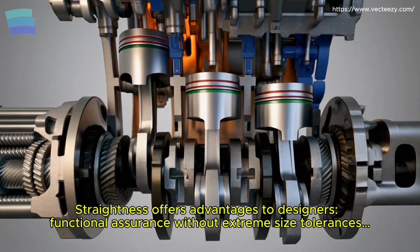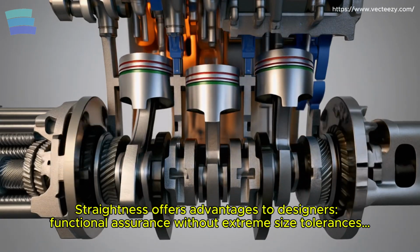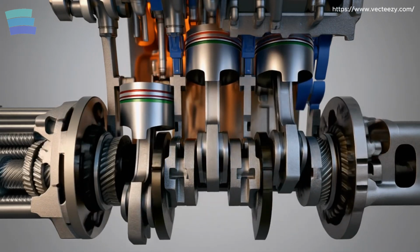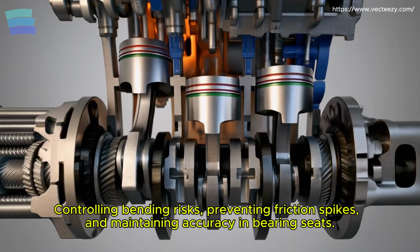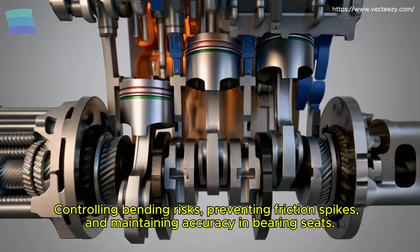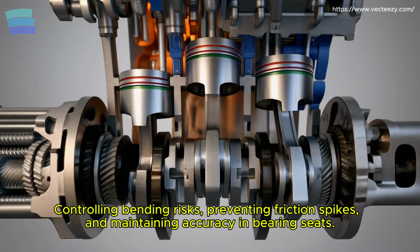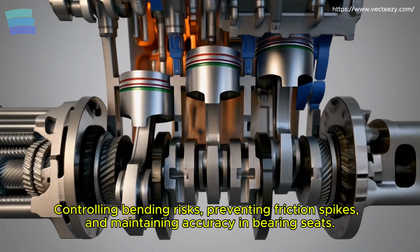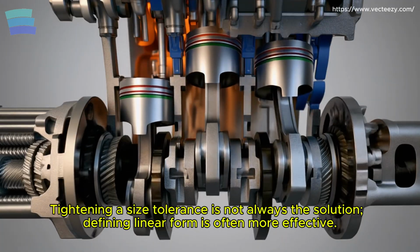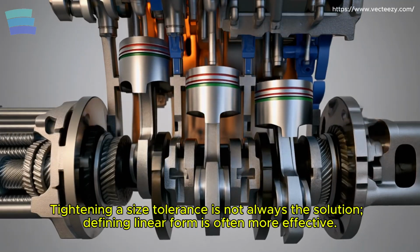Straightness tolerancing gives the designer several advantages: ensuring function without forcing overly tight dimensional tolerances, controlling bending risks in long parts, preventing friction spikes, binding, or vibration during assembly, and maintaining directional accuracy in bearing seats and sliding surfaces. Tightening a size tolerance is not always the solution. Clearly defining the linear form is often far more effective.